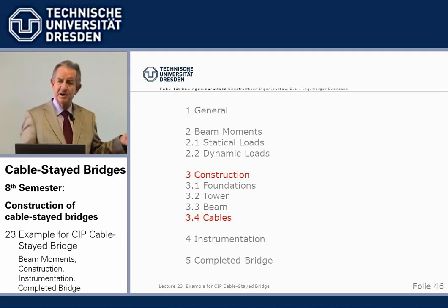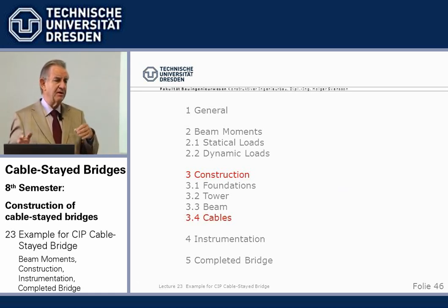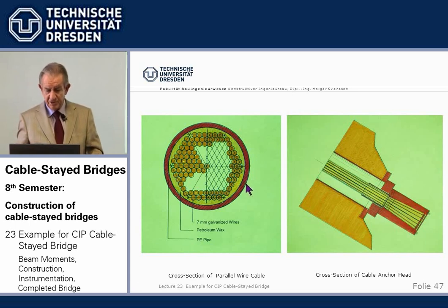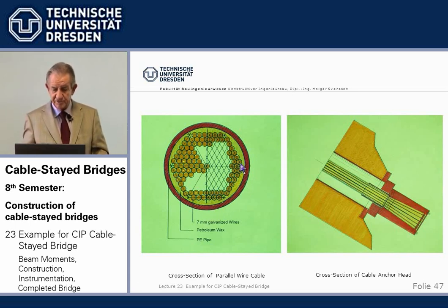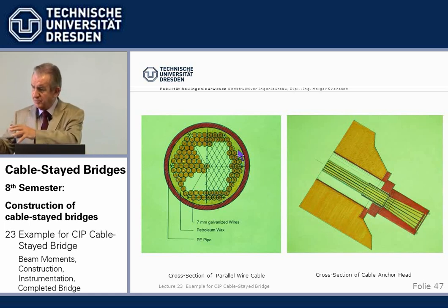The first ones we had, for corrosion protection after installation, we had cement grouted. Now here at the polar circle, in winter, it was too cold for the cement grout. So for the first time we used some petroleum wax, which can be inserted in a shop and is flexible enough that we can still use reels to transport the cable on site.